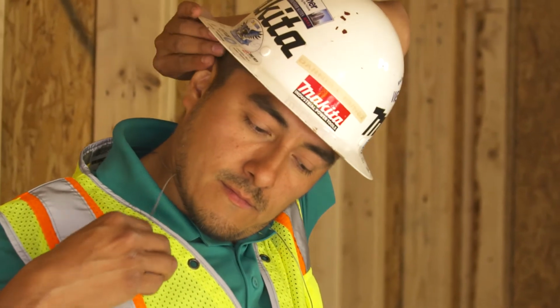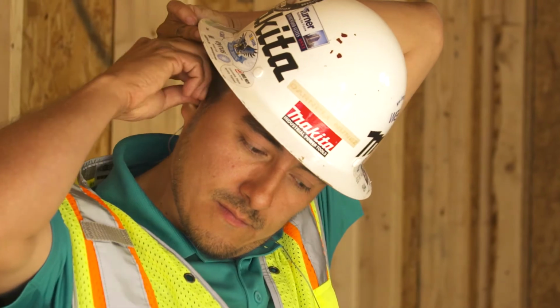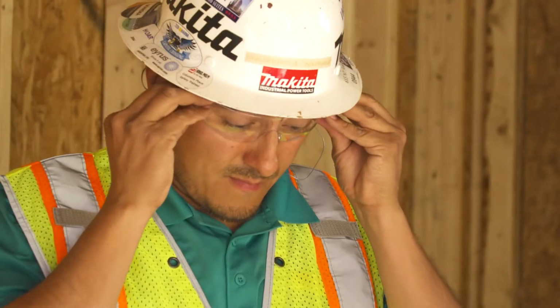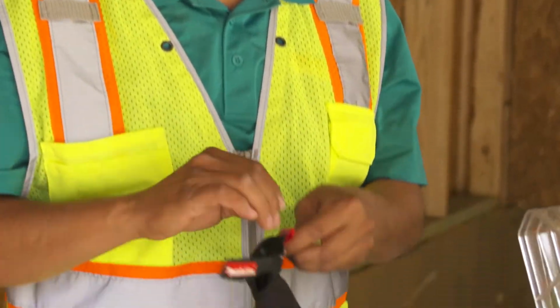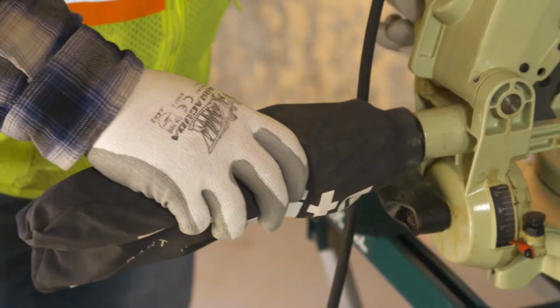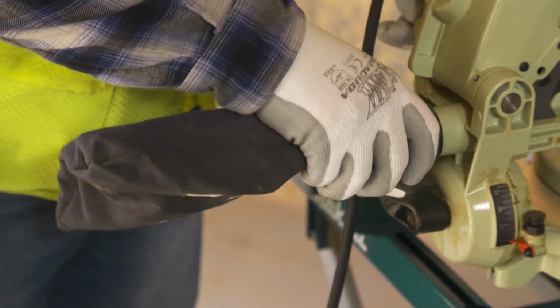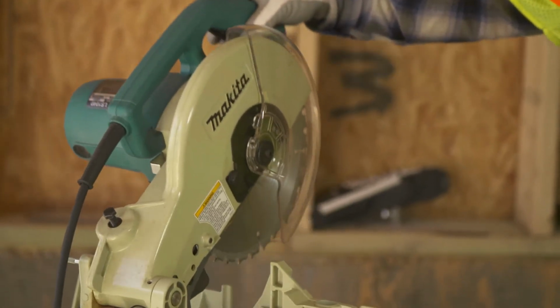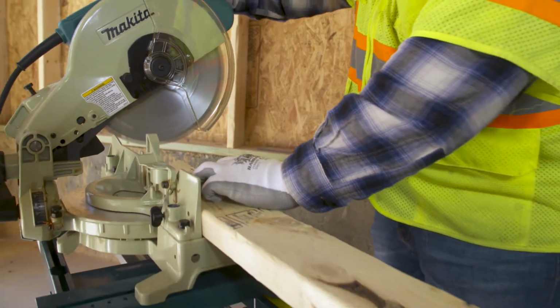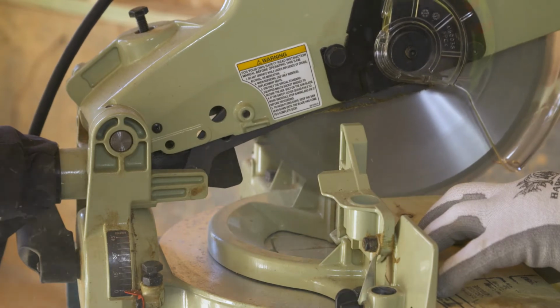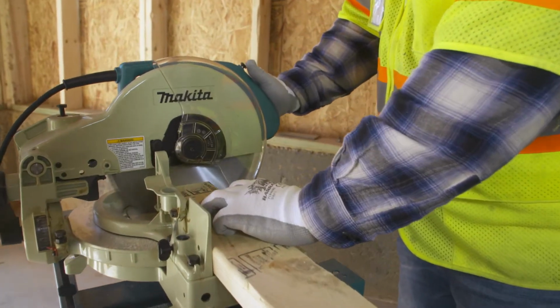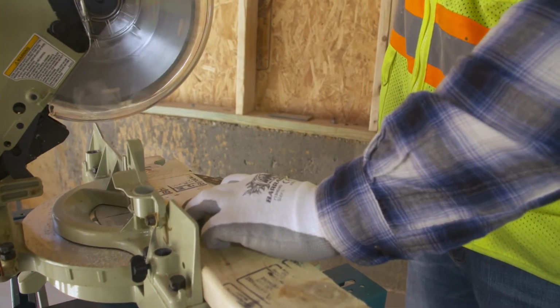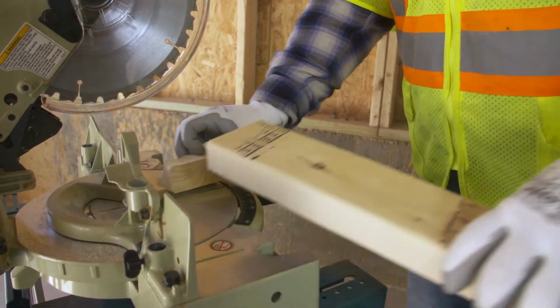To avoid injury when using saws, wear the proper personal protective equipment, including proper eye and face protection to protect against flying wood dust, chips, and particles. Ensure all blades and rotating parts are guarded, and avoid wearing loose clothing and jewelry that could easily get snagged. The operator should always be aware and take extra precaution regarding the placement of their hands, and keep them out of the line of the cut.